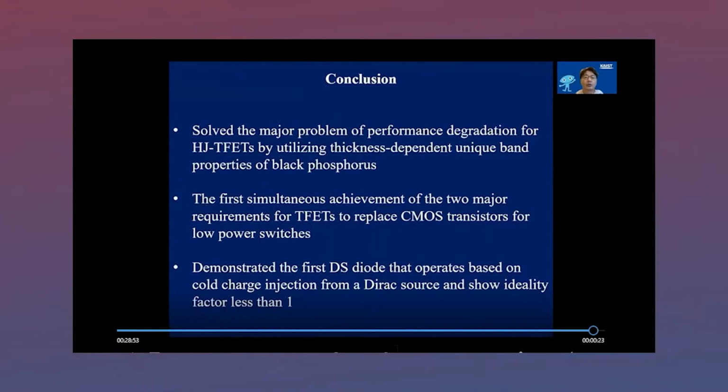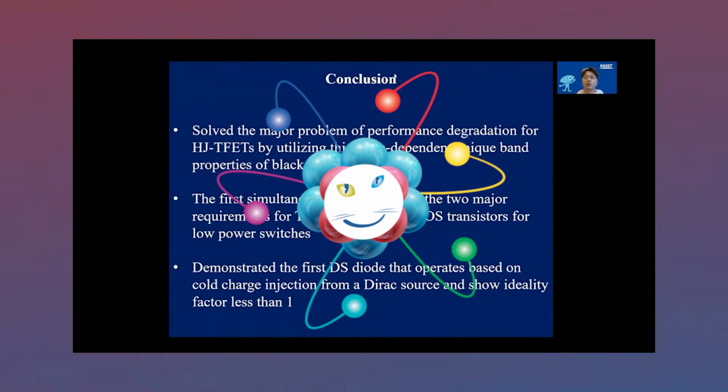Microampere per micrometer. We also demonstrated recently the first Dirac-source diode that operates based on cold charge injection from the Dirac-source, and we demonstrate ideality factor for the first time less than 1. Thank you very much for your attention.